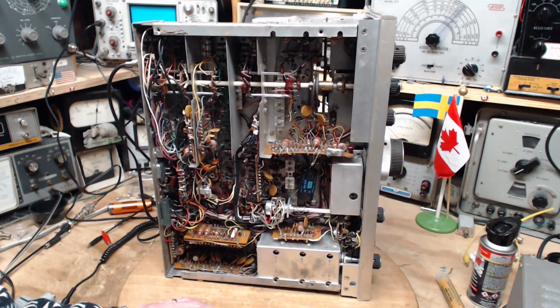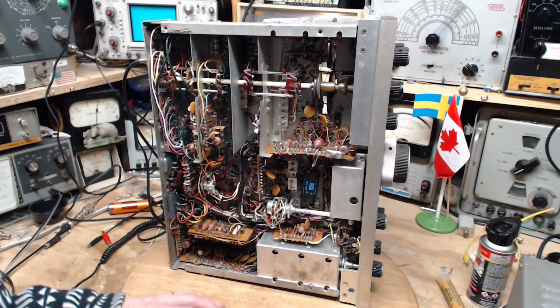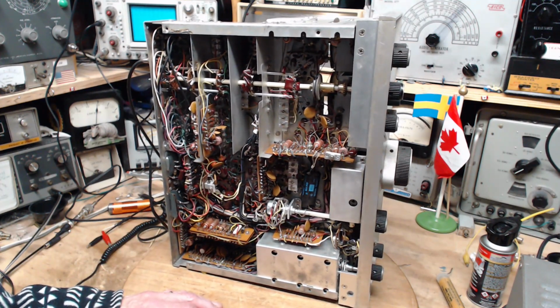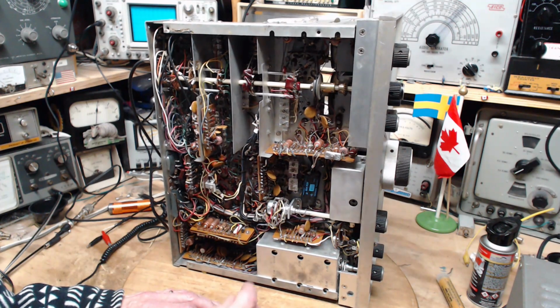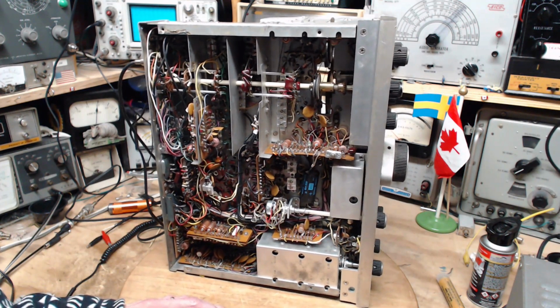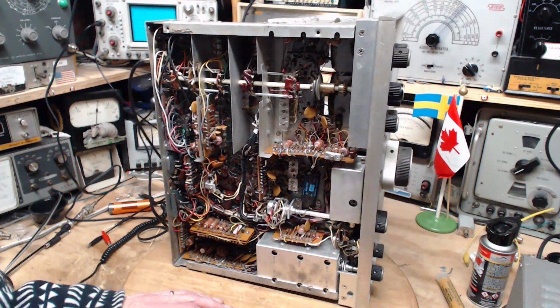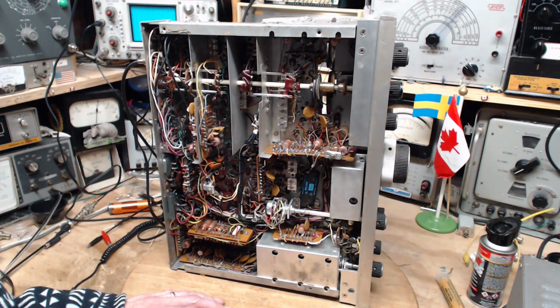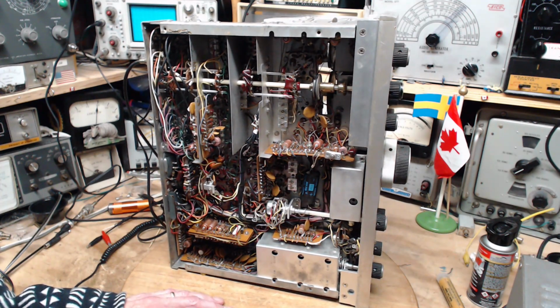So I was a little surprised to learn that. The way they do this is they alter, I believe it's the emitter voltage of one of the IF amplifier transistors enough that it stops operating. And from what I've read, that's the difference between 12 and 11 volts, which, okay, this makes me very uncomfortable.